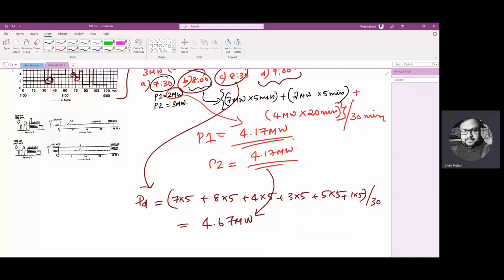Now we will move on to tariff based upon power factor. As I already told you, we have AC machines such as induction motors or transformers which absorb reactive power to produce their magnetic fields. So the power factor of these machines would be less than unity, and consequently the power factor of the factory in which they are installed will itself go down. So a low power factor increases the cost of electrical energy. That will be demonstrated by another example.